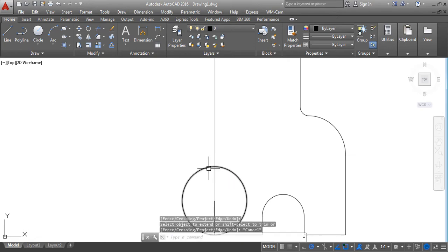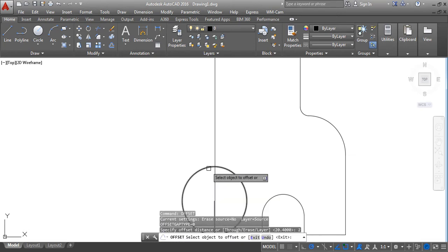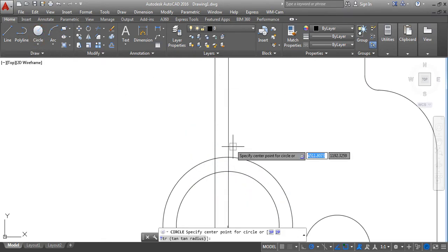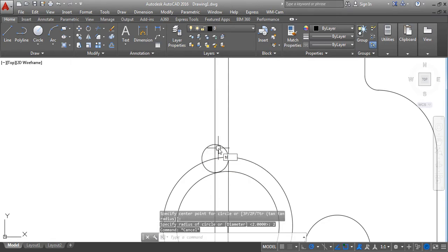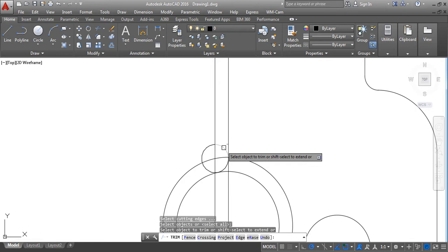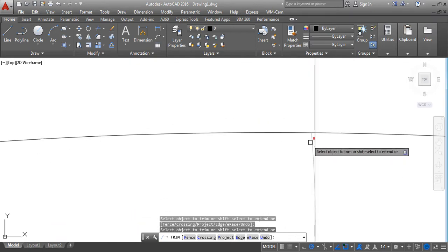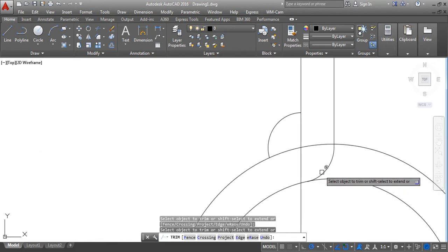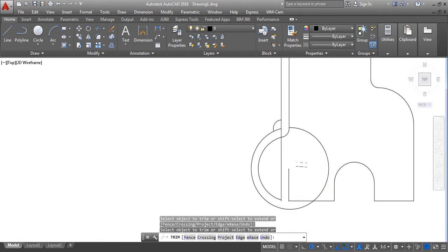As you can see, we don't have the same center, so you couldn't use this one and assume it's exactly the same center. So now we can say offset distance 2, because we need to make a fillet. We make our fillet 2, enter, and then come with trimming. The same thing that we did on the left is the same step you can take for trimming. We trim unnecessary information so that we can at least be left with what we need.